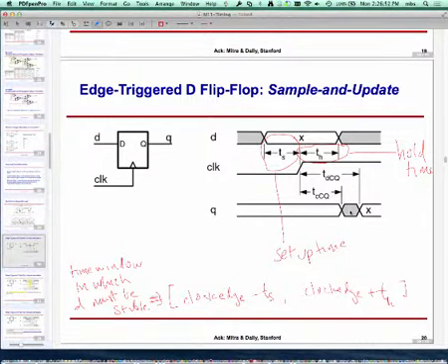This particularly becomes important if you are looking at registers. Let's say a state register, the old value was all 0s, 0, 0, 0, 0, for a 4-bit register. And the new state is 1, 1, 1, 1. Now 4 bits have to change. They may not all change at the same time. So it's possible that from 0, 0, 0, 0, I may go to 0, 0, 1, 0, then 0, 0, 1, 1. Gradually the bits may change and ultimately settle at all 1s. So there would be a period of time in which any observer looking at the output can potentially see incorrect values.